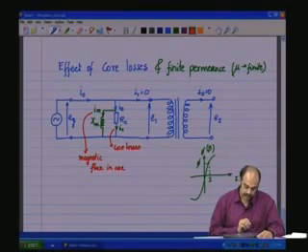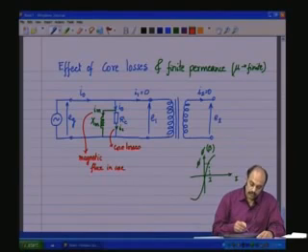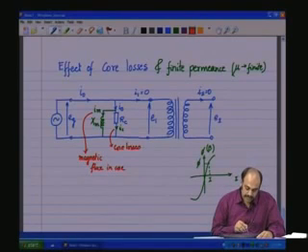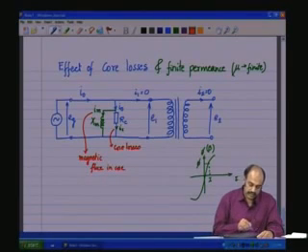How do we measure this? So, you see that IC is producing a loss in RC, IC square RC. So, the voltage across RC and E1 will be in phase, which means IC will be in phase with E1. E1 is same as EG.